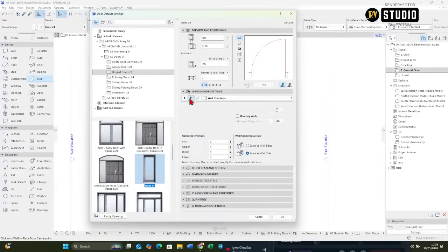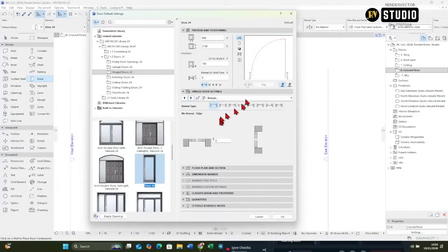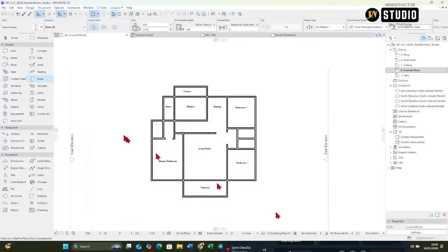So when going left, you're going to see what we're explaining. When you place your door, it stays at the edge of it, flushes with the wall. But I don't like that. I want it to be in the middle. Then I'll now adjust. Let's make this 100 and see the position here. So the door when placed is going to be in the middle, and that's how I want it. So this particular setting now is done, and I'm going to drop the door first.